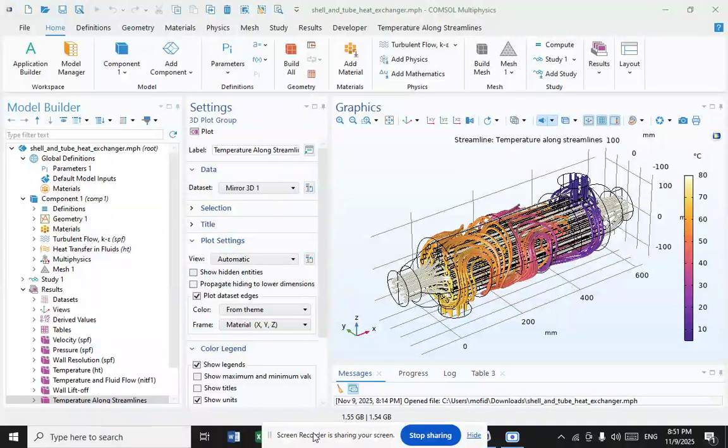This is usually a solid to liquid phase due to the small volume difference between these states. This change of phase effectively acts as a buffer because it occurs at a constant temperature but still allows the heat exchanger to accept additional heat.